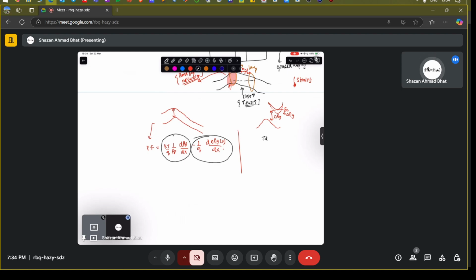You know that drift current is basically n q mu E, which is n q mu, with minus 1 over q times dE_c over dx. The q goes, so you can write it as n mu dE_c over dx. So the drift current is proportional to the slope of the conduction band profile, or the valence band profile if we write it for the holes. This is for the electrons.